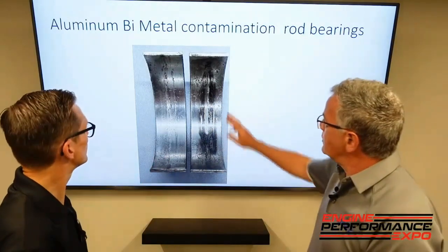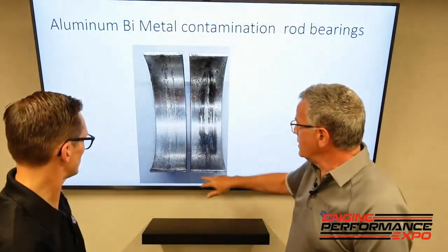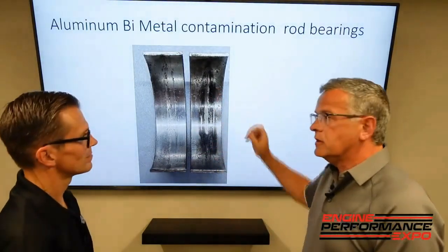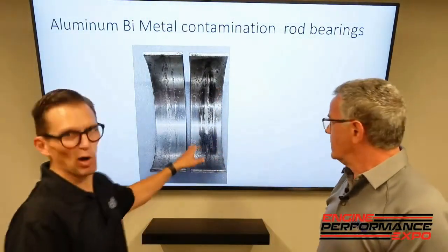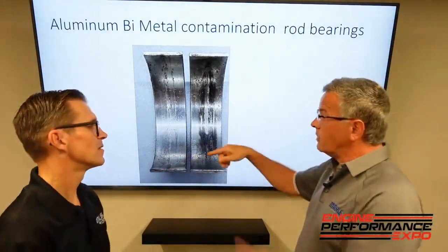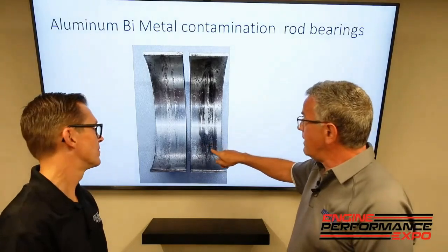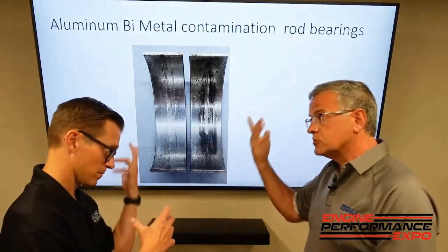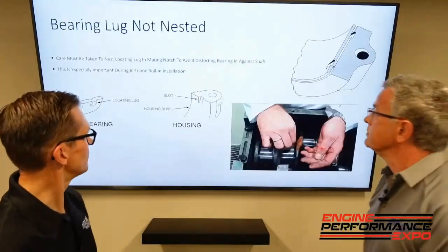All right. And this one, as you can see, again, debris. You can see the discoloration. Anytime you see black, it's heat. Yeah, exactly, it's heat. That's burnt oil, burnt oil sticking to it. Exactly. So based off the previous slide, the next thing that's going to happen is you're not getting oil, the bearing's going to get hot, close, it's going to spin. Same thing's going to happen. All right, that's the mode of failure.